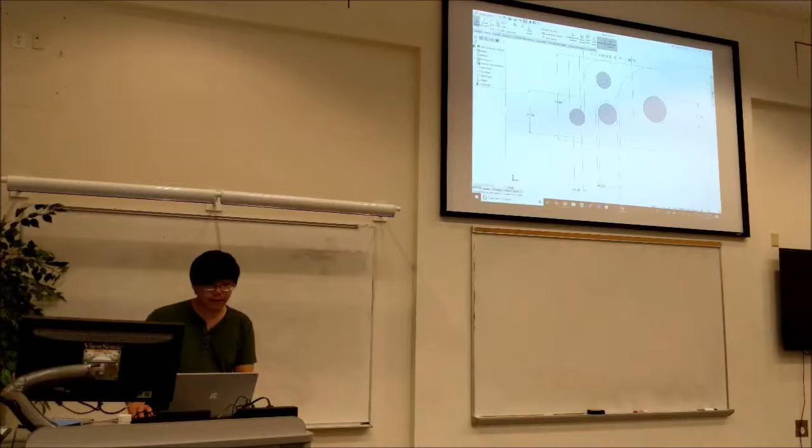One more thing we have to do for the 775 Pros is basically the motor mounting. So the 775 Pro has two M4 screws that keep it connected to the gearbox. So we're going to model like basically a center or a midpoint line from both of the motors, and then we can set these equal. And then we have the two mounting screws for each of the motors. And then we can set all these equal as well because they're the same screw.